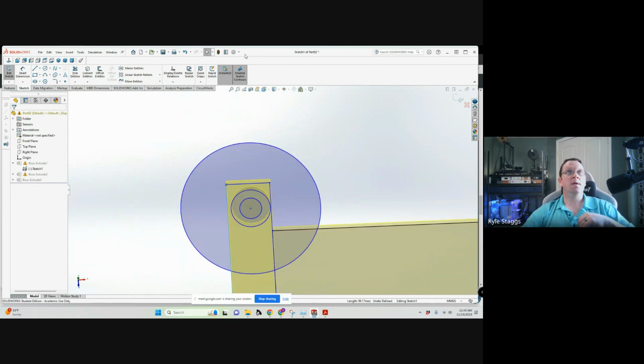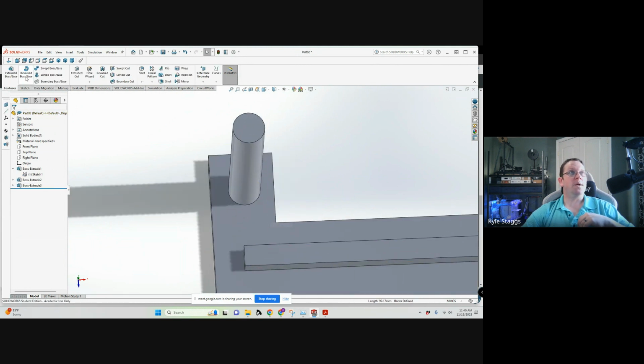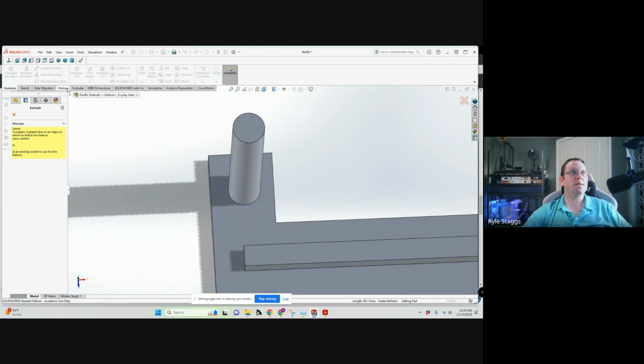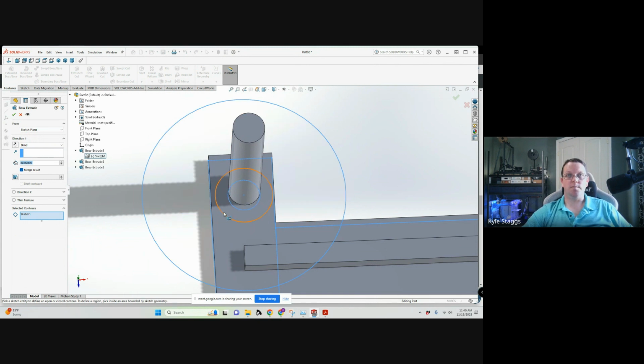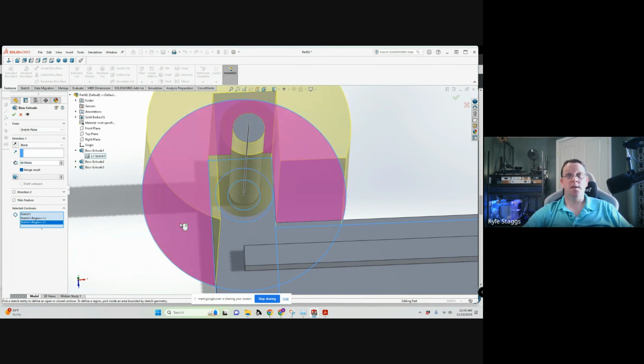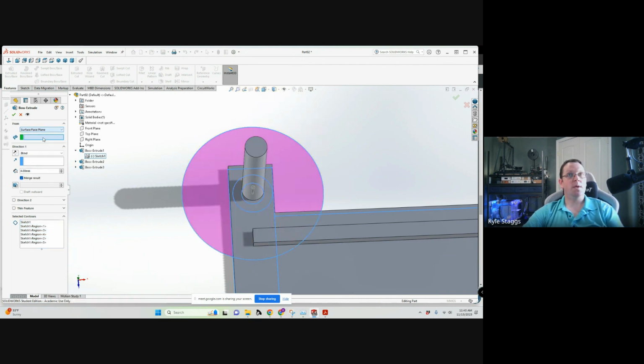So I'm going to step out and rebuild the part. Now I'm going to go back and do the base extrusion from sketch one. Whenever there's conflicts within the geometry like that, it's really hugely problematic. But I want to take all of those regions and this center section, all of those, and take this up 4 millimeters from the face, which is this one.